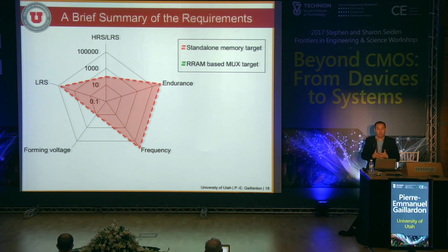a wrong estimation for an FPGA. Such a technology won't be efficient to create a RRAM-based FPGA. But this is actually just the way you use an existing technology, resistive RAMs. You program them and you use them with the level of energy that you need to target a specific application, standalone memories. If you start using them outside of this range, you can actually play within this spot where you'll basically get a much larger resistance window, but pay the price of a lower endurance.